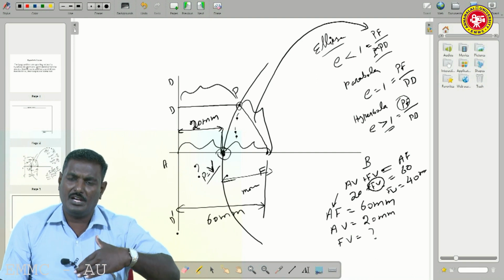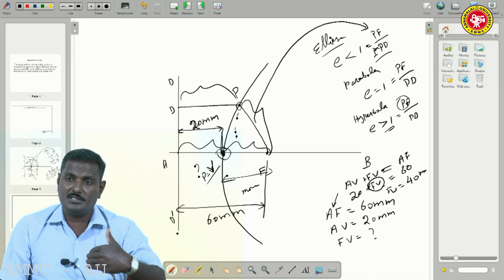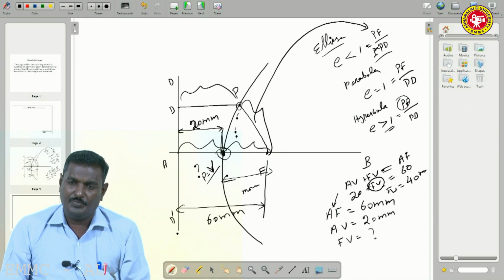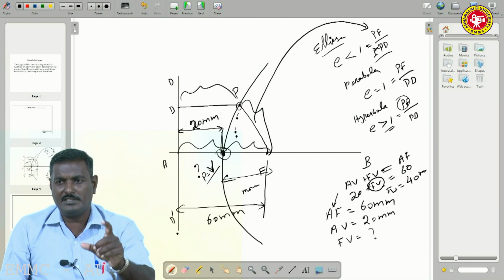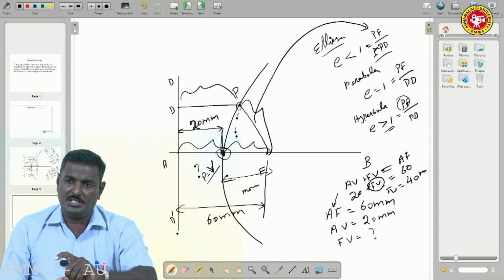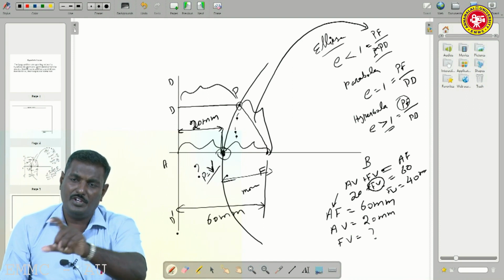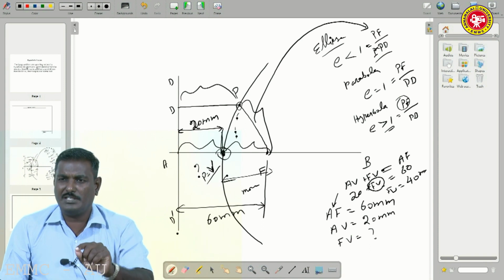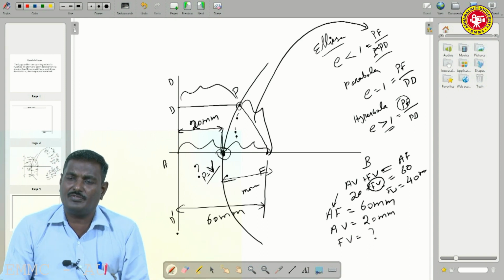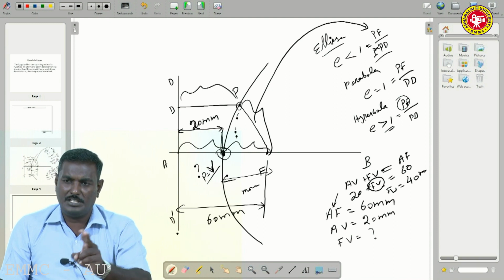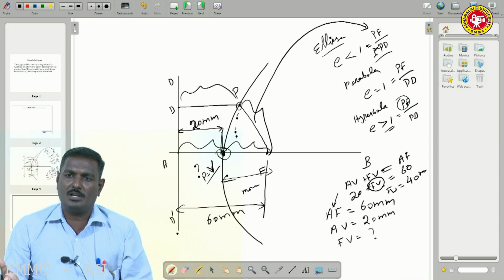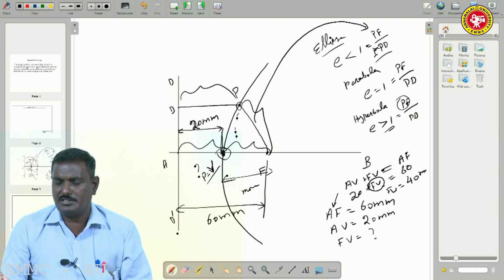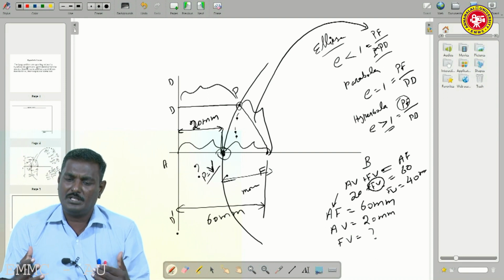If you draw a 45-degree line from the focal point that intersects the extended line AE, then from that point you draw a perpendicular line to intersect the axis. The distance between that intersection on the axis and F is equal to FV2. This only checks the other vertex of the ellipse. For the parabola and hyperbola, there is no need to check this, because for an open curve there is no other vertex to check. So it is very simple, and also easy.